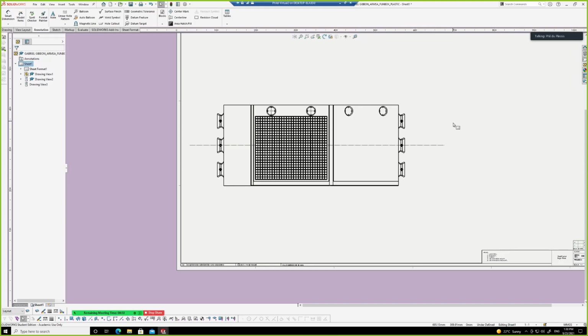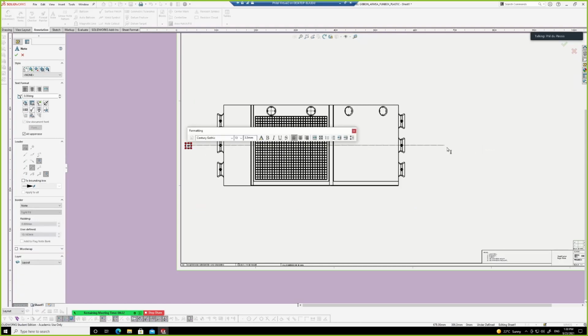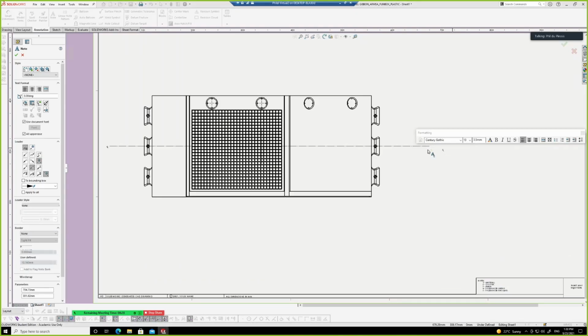Remember last week we spoke about center line being three different things. If it goes through the object through its center, that is also a center line, but you can only call it a center line with a CL on the end if it actually halves the object. And you must put center lines in at both ends of the lines, by the way, not just one side.